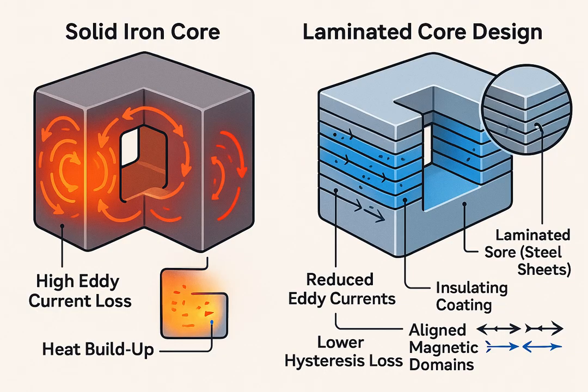So far, we've seen that the magnetic core in a transformer plays a crucial role in guiding the magnetic field efficiently between the primary and secondary windings. But using a solid iron core isn't a perfect solution. Here's why. When the alternating magnetic field from the AC current flows through the core, it doesn't just passively move through it, it induces eddy currents inside the metallic material.